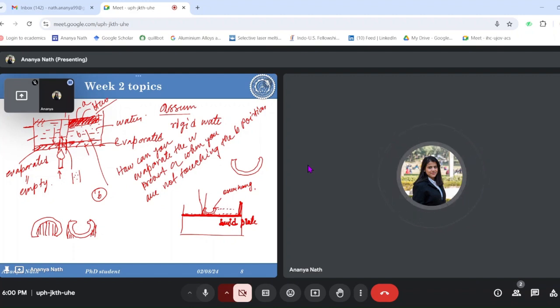Now here one can say the powder particles are present, so the powder particles can act as a support structure. What is the issue in it? The issue is there is a difference between a solid part and a powder part. So here the support is powder, and I am interested to build a support which is solid. Why? Because when the laser is coming from the top head, the laser will transfer the heat to the powders so that the powders can get melted and solidified.